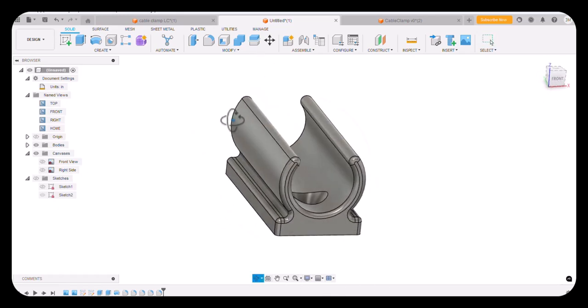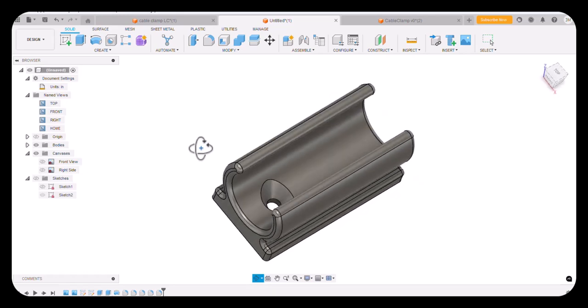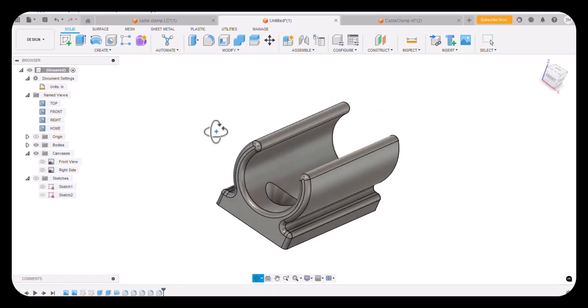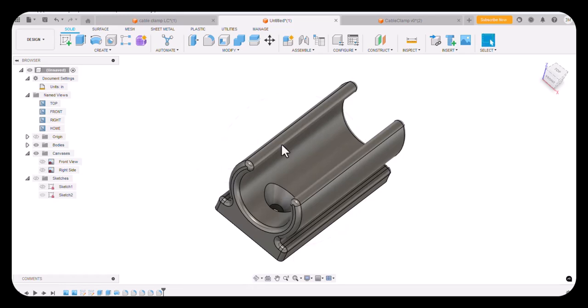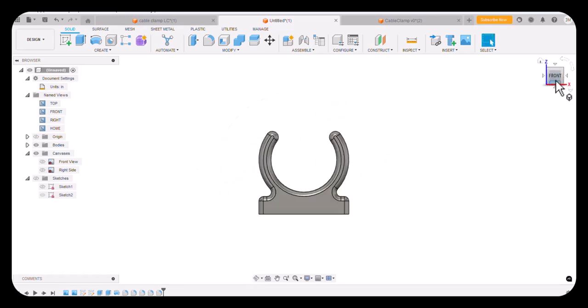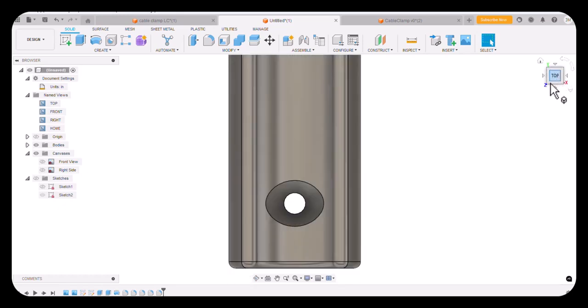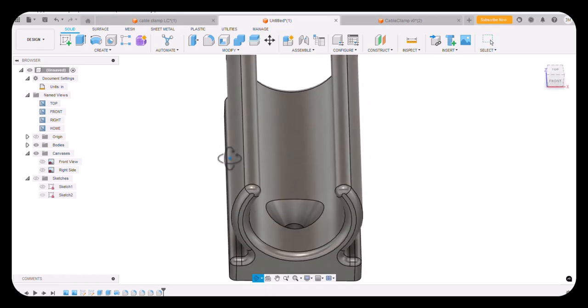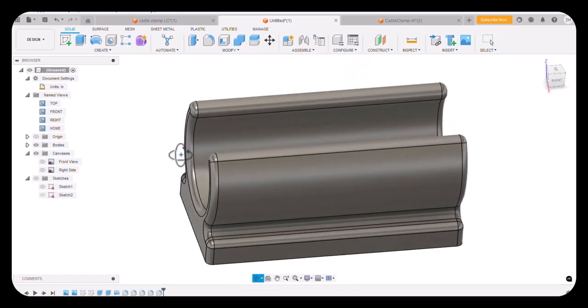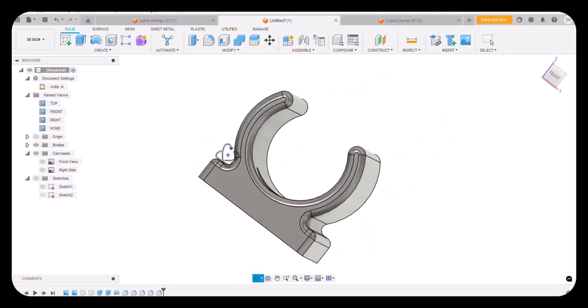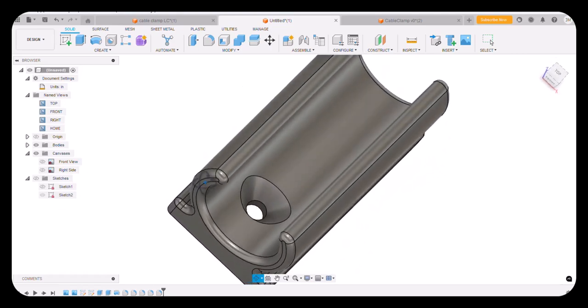Now we end up with a situation, we're going to 3D print this. No matter how we 3D print it, we're going to have an overhang. The question is, which way is the overhang going to be the most difficult issue? So here we're printing, it's going to be unsupported out here, but can this geometry support it? And then the other option is, no matter how we orient that, we're going to have unsupported edges. So we have to decide which way will work best for our printer.